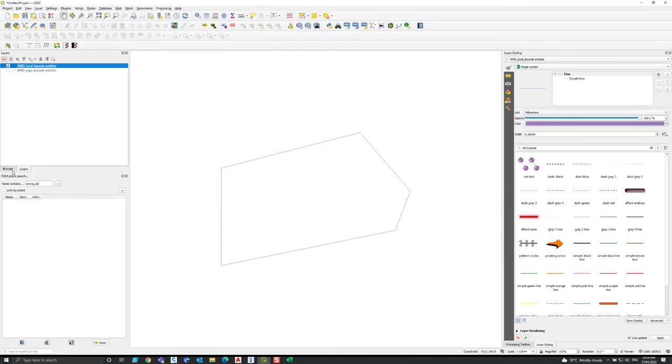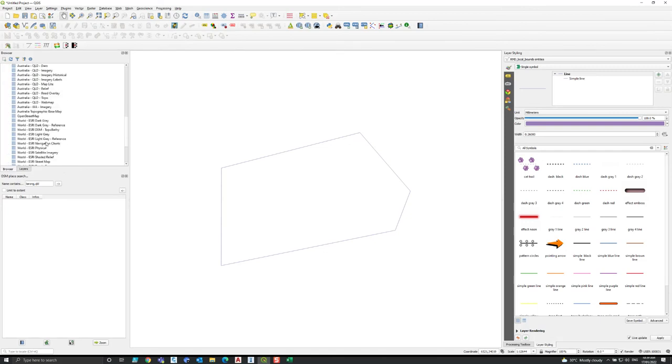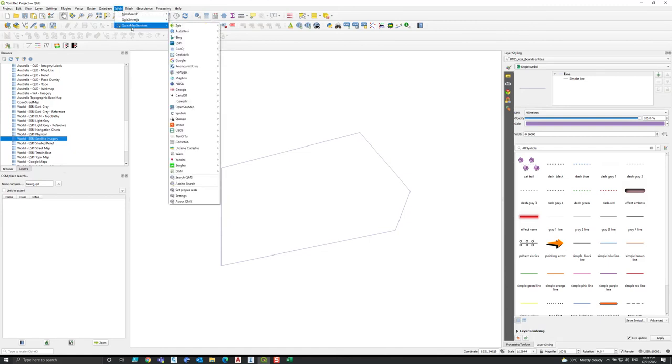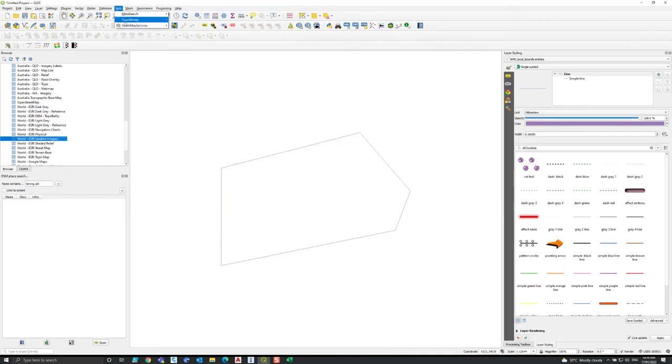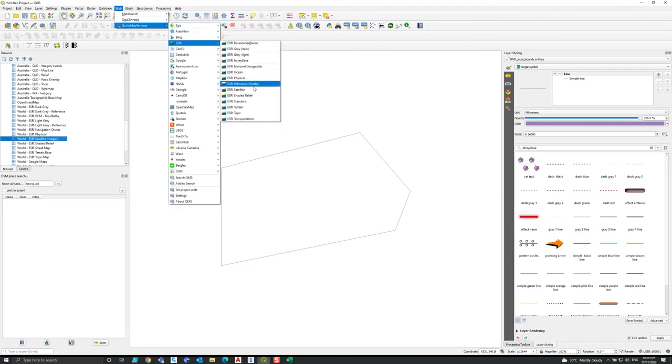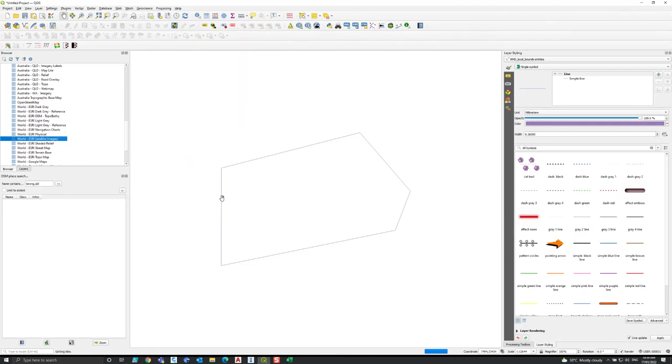And we should be able to bring in imagery and see that it's the same. So you can bring in an XYZ tiles thing here to get Esri satellite imagery. If you don't have imagery in QGIS, you can go install the Quick Map Services plugin. Initially, you won't see all this imagery here, but if you go to settings, you can go into the More Services tab here and hit Get Contributed Pack, and that will give you all these other services you can see here. The one we want to use is Esri satellite imagery.